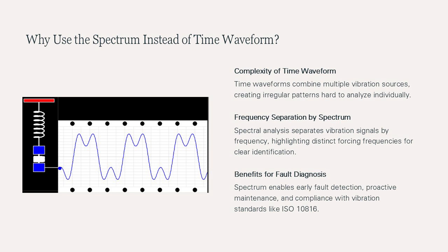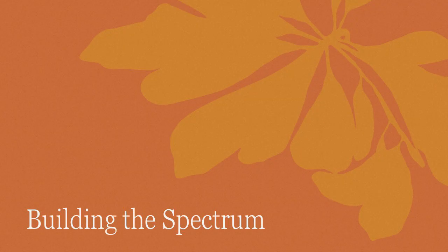By focusing on frequency-specific data, analysts can identify faults early, plan maintenance proactively, and avoid catastrophic failures. In short, the spectrum transforms complex vibration data into actionable insights, making it indispensable for effective machine diagnostics. The role of FFT in spectrum generation: how FFT separates complex signals.